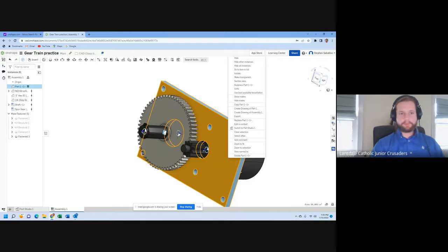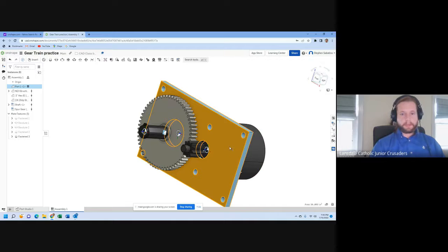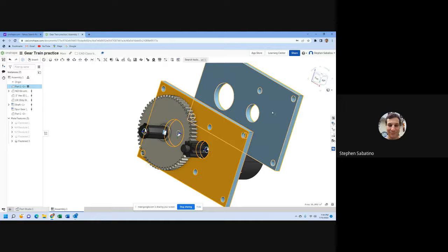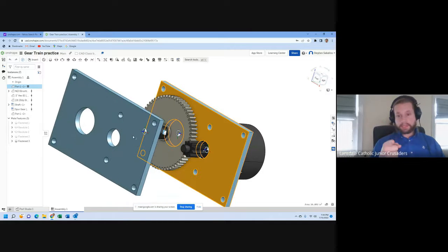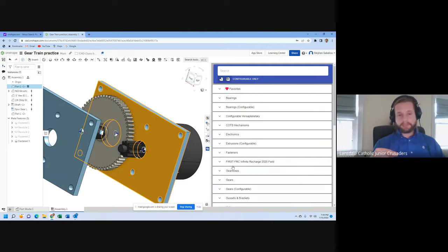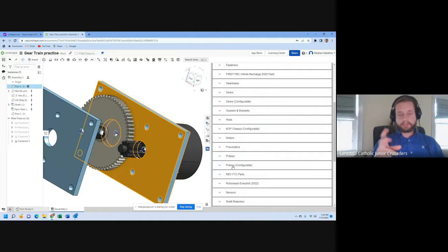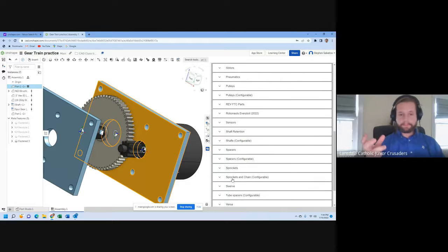So click on your part. You might have to click on it over in the left pane. Yeah, there you go. Copy part 1 and then Control V or paste. And there you go, you've got 2 of them. What's cool about this is if you make any changes to the other one, they'll automatically happen to this plate as well, because they're the same part. If you needed to make them unique parts, you do what I did previously, which was that transpose function, and you make it a copy.